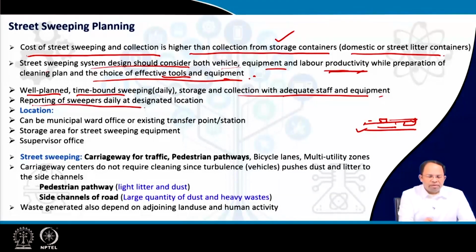Then we also have to designate locations where sweepers will report every day, because it's a big manpower that reports every day and takes up certain stretches for cleaning. There have to be supervisors looking into who will work in what stretch and whether they're working properly. All this needs to be planned. Everybody has to come to a point where they change, take the equipment, and then go for work. That's why the location is very important. It can be either a municipal ward office or a transfer point or station where all this equipment is stored. In addition, there may be a supervisor office there, changing rooms, and cleaning rooms could also be present here.